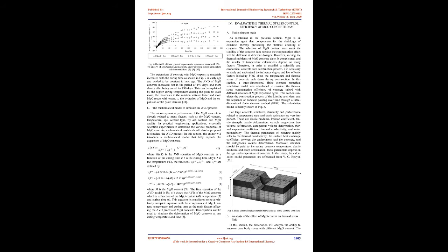The AVD of MgO concrete increased fast in the period of 190 days, and more slowly after being cured for 190 days. This can be explained by the higher curing temperature causing the paste to swell more, the molecules in the solution activate faster and more MgO reacts with water, so the hydration of MgO and the expansion of the paste increase [31]. See the mathematical model to simulate the AVD process.